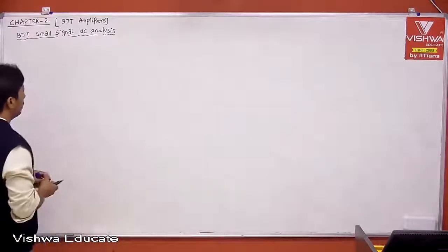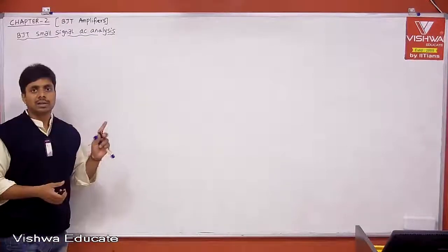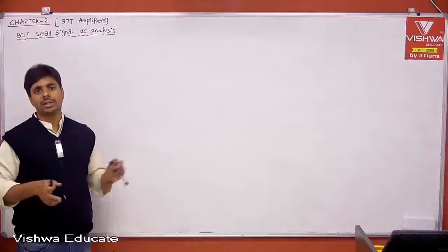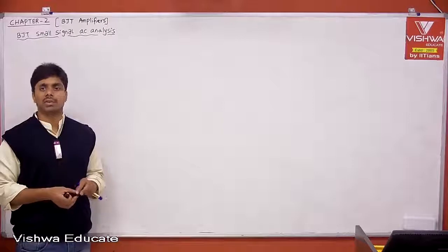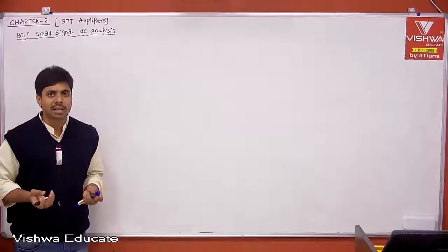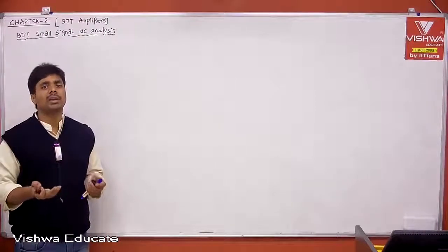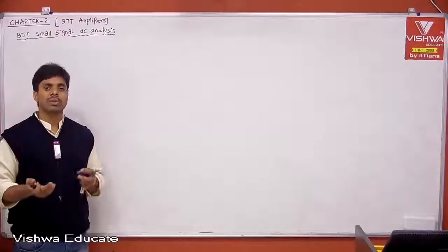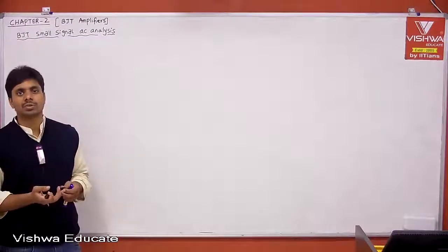In the last session, I told you that when you take switch action or amplifier action, it is only a steady state equation or DC equation where timing information is not there. But if I incorporate timing information, that is nothing but AC analysis. Let's see, at a given frequency which is not zero frequency and not infinite frequency, how the equivalent circuit will change, which is basically a dynamic circuit, or dynamic resistance if it is a two terminal device.